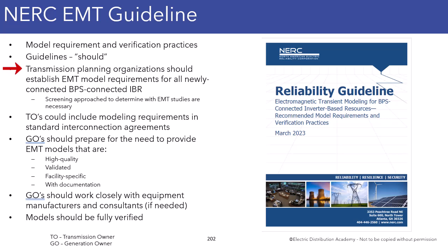And transmission planners can still apply a screening to determine when EMT studies are necessary. Transmission owners can include modeling requirements in their standard interconnection agreements, and then generation owners should prepare for the need to provide EMT models that are high quality, validated, facility specific with documentation. In other words, not a bunch of junk, right?